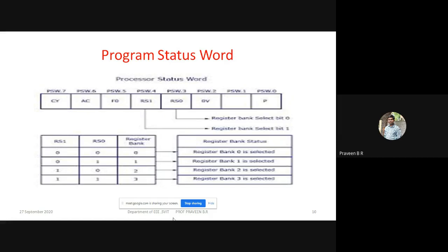Let us start from parity. What is a parity? Let me say I have 8-bit data in an accumulator. An 8-bit data is usually a hexadecimal number, and hexadecimal numbers are usually represented by zeros and ones. So, if there is data in the accumulator, it is going to check whether there are an even number of ones or an odd number of ones.